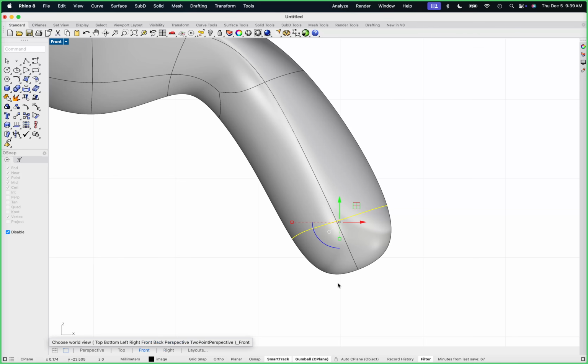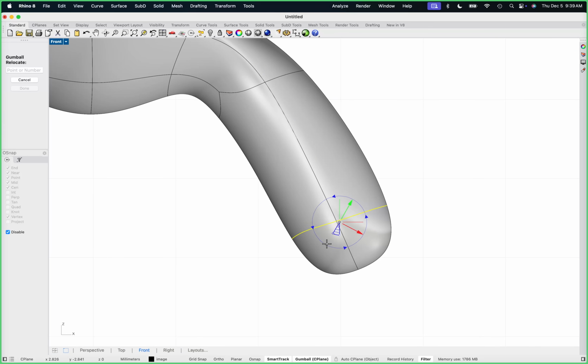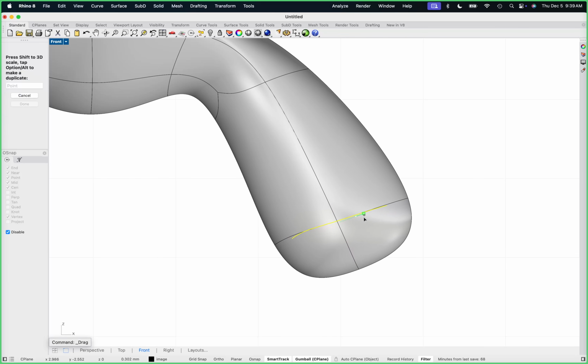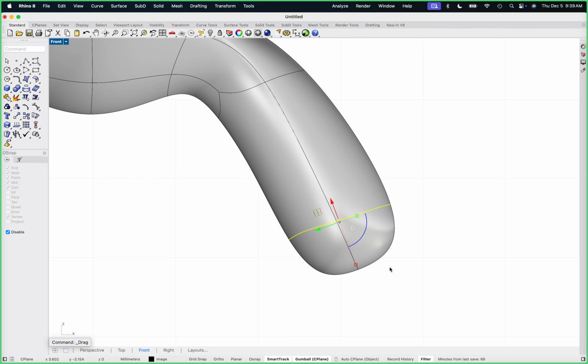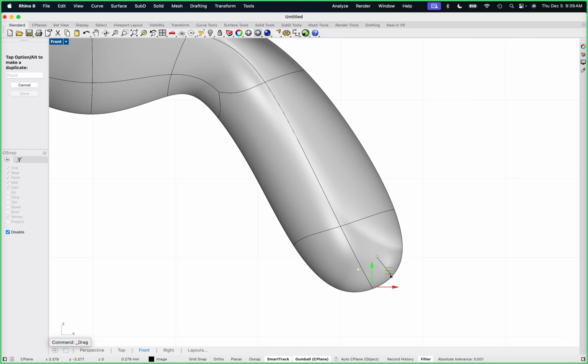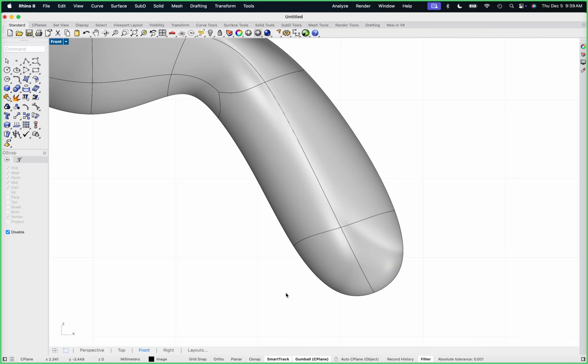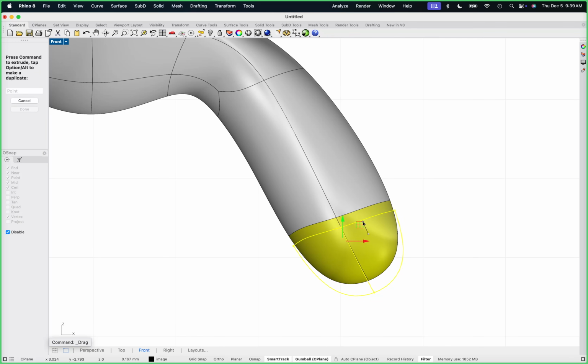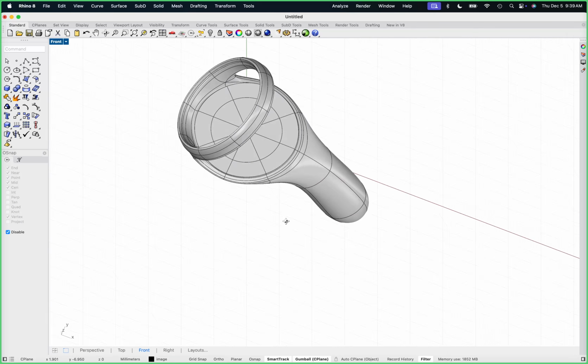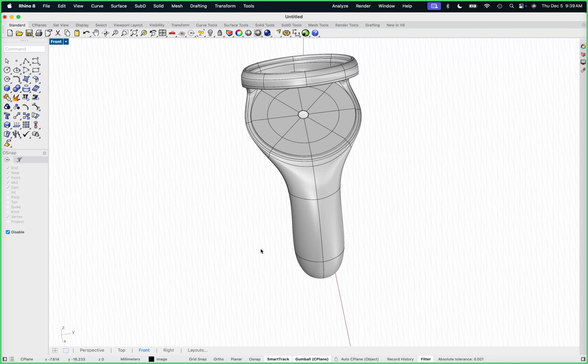To get the tall out of that, I'm going to double click and snap my gumball to just vaguely align with that, and then use this handle like that. I don't like this shape down here, so I'm going to drag this point, get it a little rounder, and then maybe shorten this whole thing a little bit. You see how we get to kind of play with it, right?